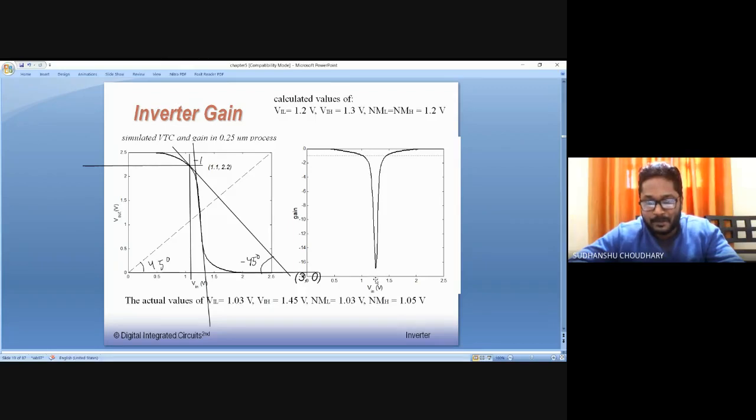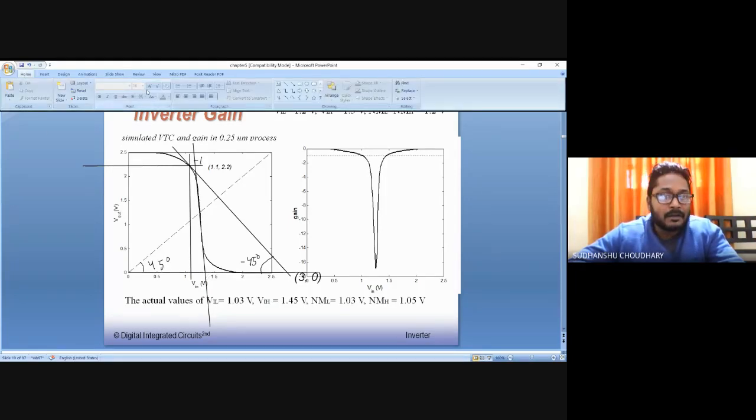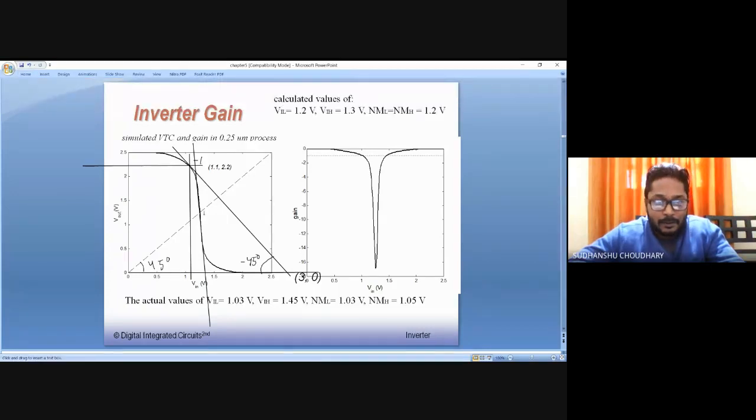You see that this is Vm, that is 1.25 volts. So at 1.25, you are seeing gain of, or dV by d out, that is slope is minus 17. Okay. So slope is minus 17. So at Vm, the same slope can be found here, right? From the same analysis. That is, you mark the coordinates at this point Vm. So coordinates are 1.25 and 1.25 here, and at this point also you mark a coordinate. So let us mark another coordinate using the same way. For this VM, that is this point, that is switching threshold, I have the coordinates as 1.25, 1.25.